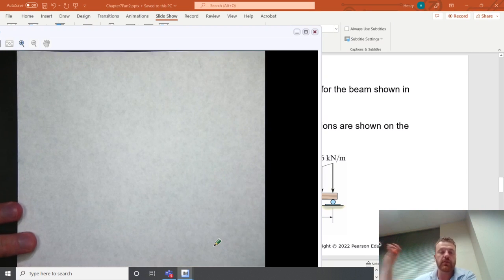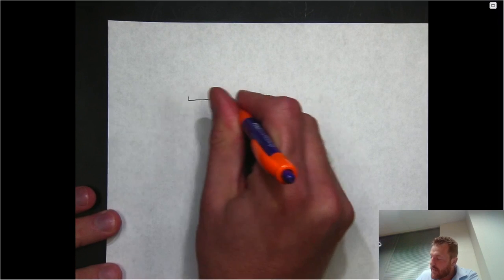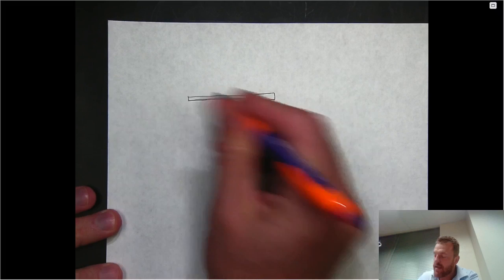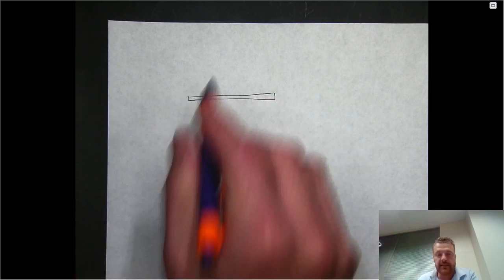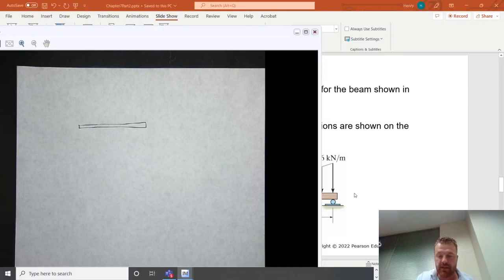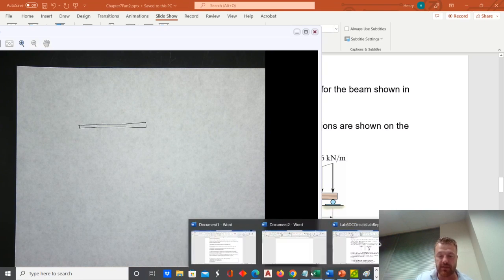And remember, those are nothing more than how the internal forces V and M vary as we move along the beam. So the first step in all of these problems is actually to determine the external reactions on the beam. And since beams are always loaded with perpendicular loads, it's not surprising that even though that pin could have a horizontal external reaction, we actually don't need to solve for it.